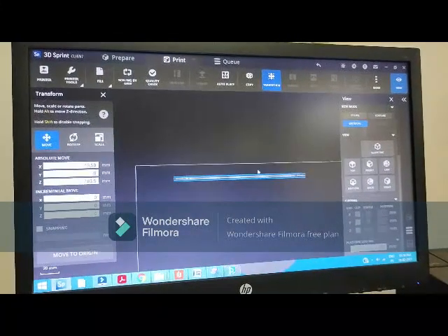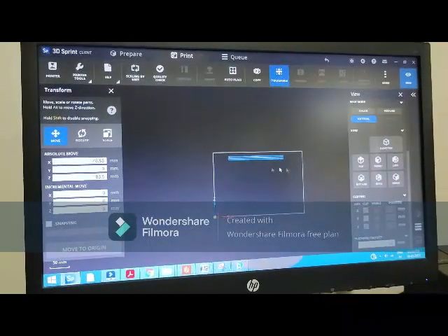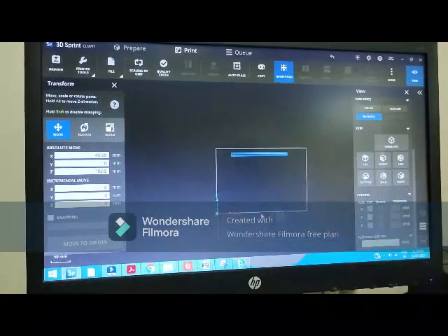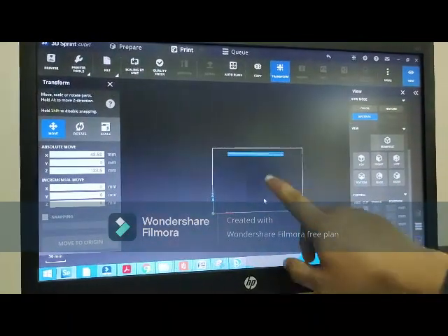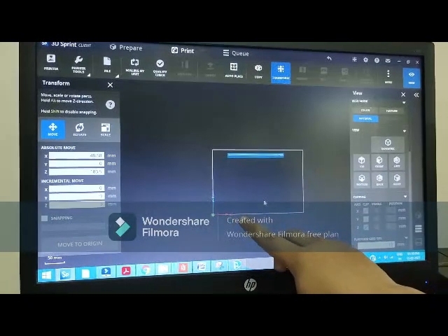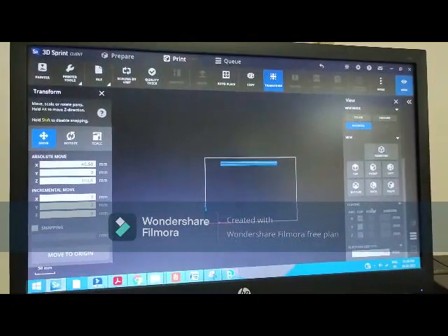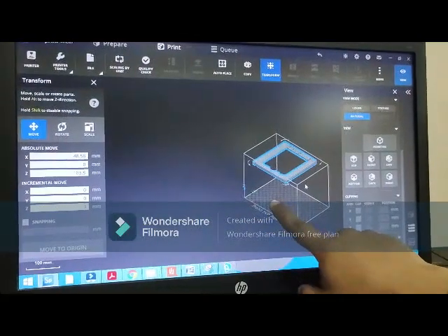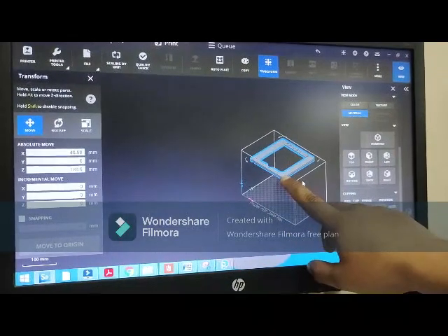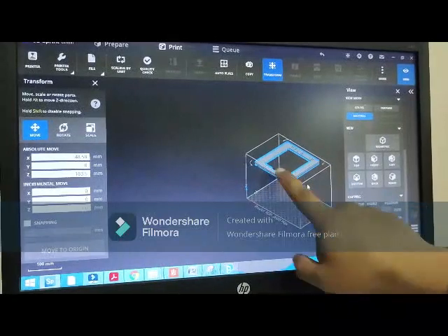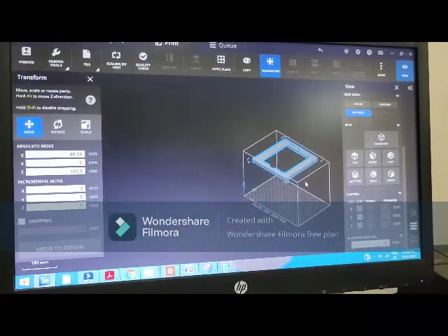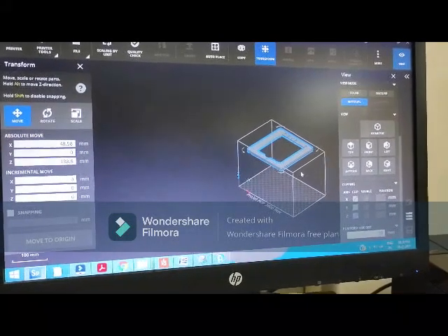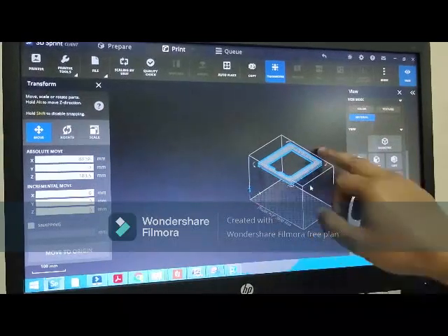Similarly, in the front view we can see the frontal portion. Now this is our base, and the part is at a distance from the base. If I print this, all this empty space will be filled with support material. You got it? From the isometric view you can see this is our base where we need the printing, but the part is at a distance from it, so this empty space will be filled by support material. This takes our time unnecessarily, and we are spending money on support material because we are filling all this unnecessarily.